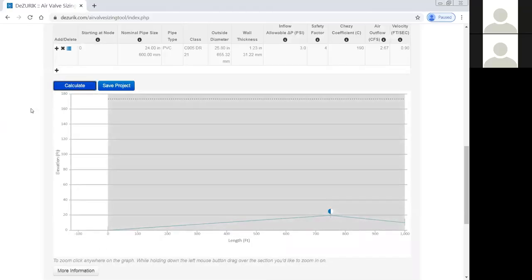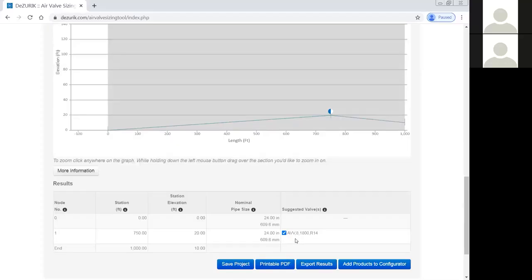So the first thing you're going to think is, well, okay, it's smoother pipe. It seems like it's more efficient. Probably, if anything, I'll use a smaller air valve. That's exactly opposite. It forced you to go to an 8-inch air valve. The reason is, if you broke the pipeline and water started flowing out of the pipe, because the pipe is smoother, water will flow faster. So you need an air valve there that can let air in faster, because water is going to rush out faster. So kind of an interesting little trivia, if nothing else.